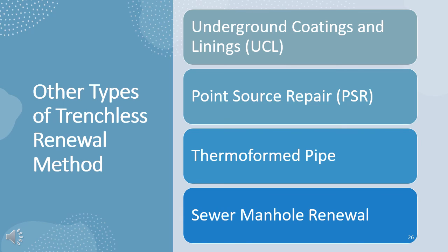it is used to avoid surface water inflow and groundwater infiltration. With this method, it results in avoiding structural damage and protecting materials against corrosion. And the physical characteristic of the structure, age, type, and condition of the site on the manhole system must be analyzed before choosing this method.